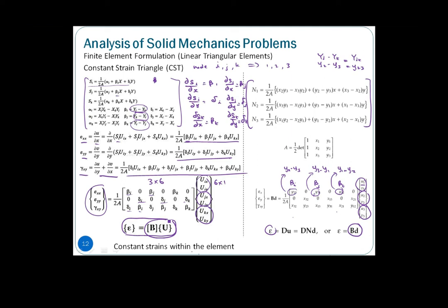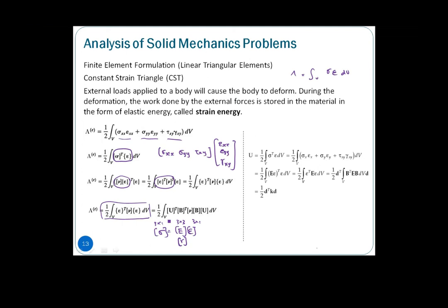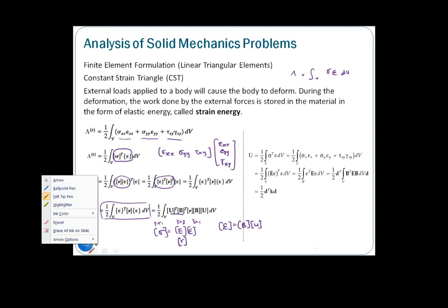With the constant strain, B is the derivative of the shape function itself. So now this itself is BU, right? So the transpose basically is U transpose B transpose. All right. So that basically gives us our strain energies.